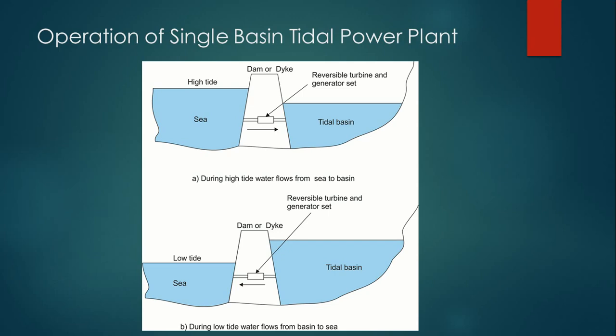The turbine continues to generate power until the tide passes through its high point and begins to drop. The water head then quickly diminishes till it is not enough to supply no load losses. The bypass valve then quickly opens to let water into the basin to gain maximum water level. When the sea and basin water levels are again equal, the valves are closed as well as the turbine conduit.